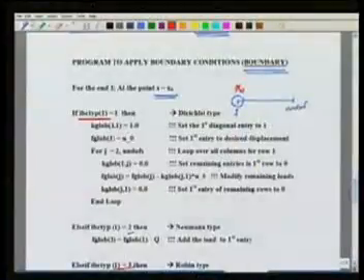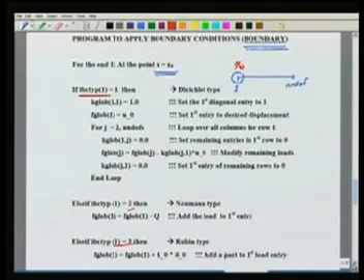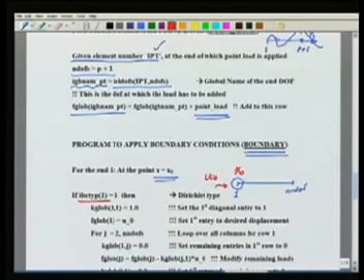So here how are we going to take care of these various types of boundary conditions that can be applied in this problem. Okay. So let us see first the Dirichlet type. So for the Dirichlet type, here I am going to specify the value of the deformation here, and this is given by u0, the displacement at this end. u0 need not be 0 always. So I am giving you the value of u0, and I want to enforce this in our calculations